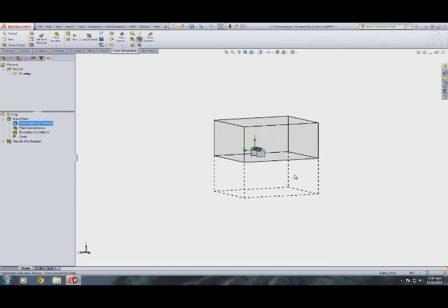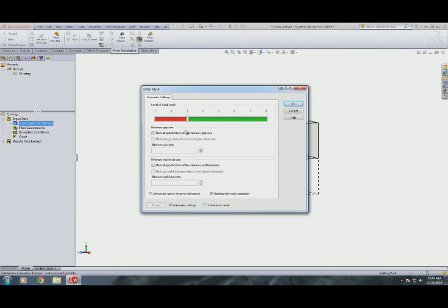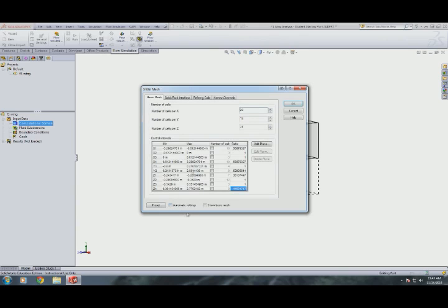Step C, mesh settings that worked good enough for me are listed on the next page. So let's skip straight to those so we don't have to sit here and iterate some mesh stuff. Obviously just the simple slider, I gave you some more detail in that, so uncheck automatic settings, and now you get more detailed stuff. Following the things on the second page of the PDF: 4, 2, 2, 5, 4.